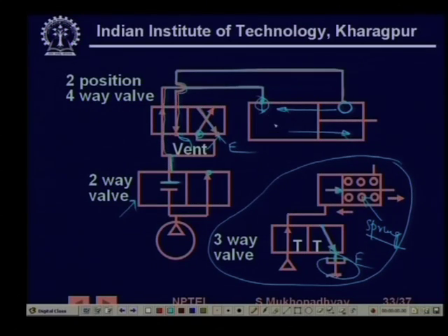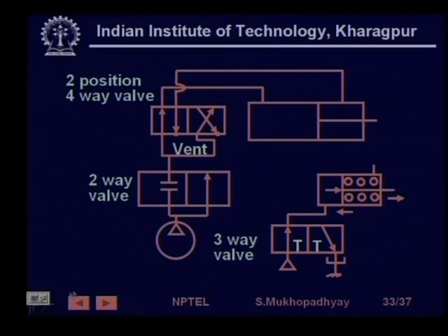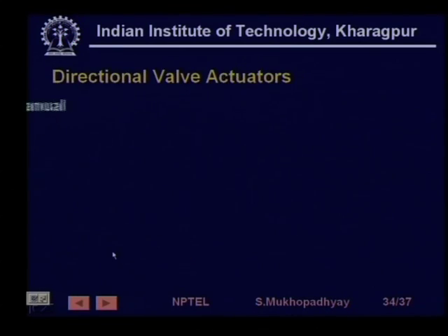So, therefore, this chamber is sealed, while this chamber is open. So, what happens is that now if you want to push the cylinder, then the air will get compressed and some force will be created. So, it cannot be freely moved. So, it gets kind of soft locked that way. So, you can have various sorts of such circuits, and we will see some of them later in our next lecture.